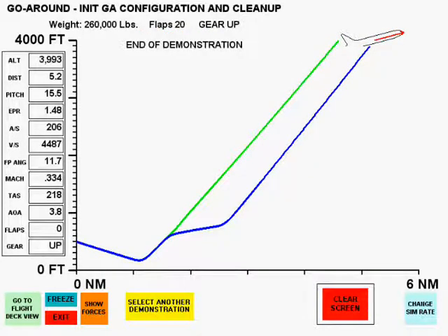This exercise illustrates why it is standard procedure to climb at the existing approach airspeed plus the airspeed gained during transition to the climb. Then, upon reaching the missed approach altitude, acceleration to clean maneuvering speed while retracting flaps is accomplished. Attempting to accelerate and clean up prior to reaching the missed approach altitude can lead to an unsafe flight path.